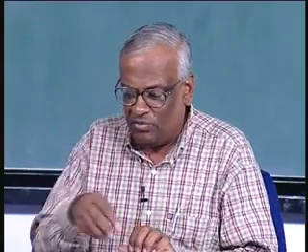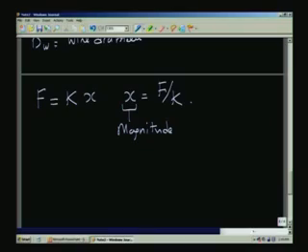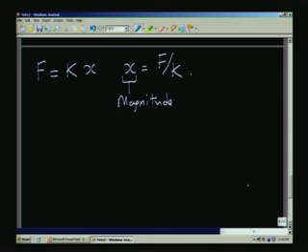And also you will see that the displacement is proportional to F by k. The larger the spring constant, the smaller the magnitude of x. Therefore, the sensitivity is also determined by this F by k. The spring constant is going to determine the sensitivity of the particular spring material. In fact, we can also have spring material not in the form of a coiled spring, as this was.